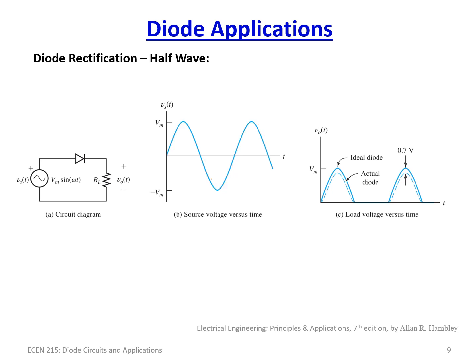Well, if you put in a diode, it's only going to allow the positive voltage through, assuming you do not reverse bias it beyond its limit. So in the case of a standard rectifying diode, where this is not exceeded, the only way you're going to allow current through to the load is if you are forward biased, which means your resulting output is going to be pretty close to the actual input voltage, naturally minus 0.7 volts because of the diode voltage drop.